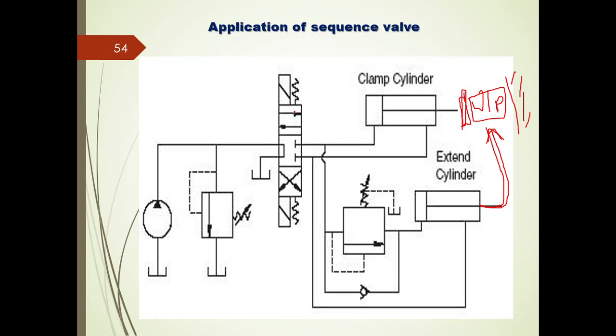So now I will be actuating the first position by supplying the electrical voltage to this solenoid, and my pump port will be connected to system port A. That means the flow will be getting to the blind end side of the cylinder, right? Along with that one, the fluid flow will also move in this direction. Here it will be blocked because of the check valve.